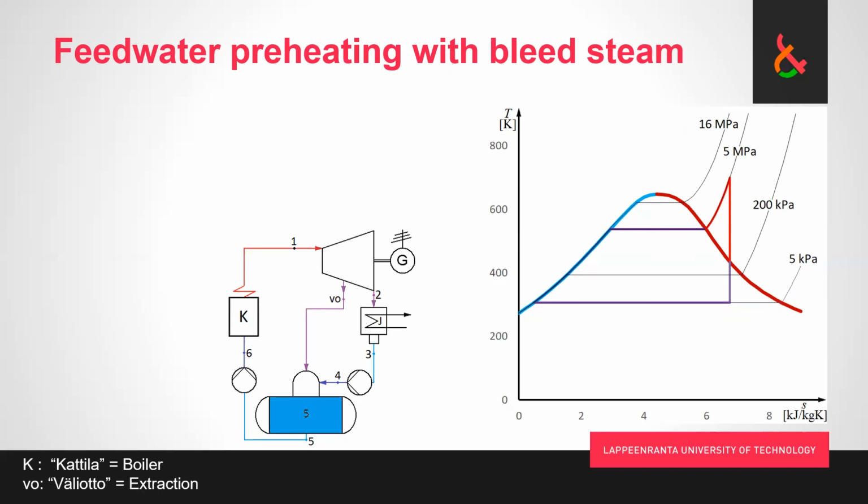And what we do with this, so basically now we are adding steam into the feedwater, and we notice that we have now two pumps, not one. So we have the condensate pump to get the feed to a little bit of pressure, then we mix steam with it. Presumably, we're going to have a little bit hotter water at this point, and then that water we fully pressurize before putting it into the boiler.